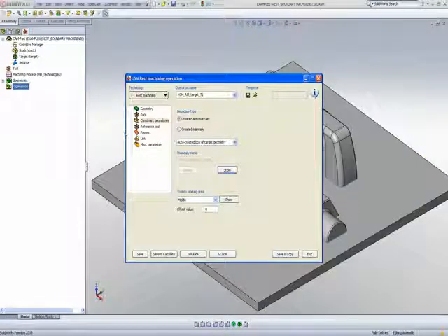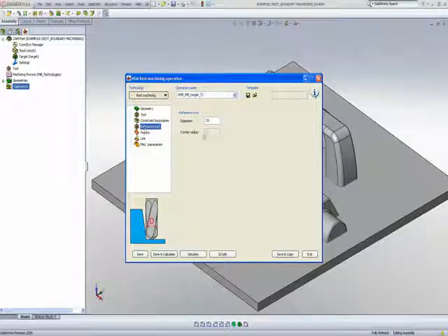And if I go into my reference tool, this is the area where I'll tell it what was the previous tool that worked there. The previous tool that I used, like I said, was an 8mm ball end mill. So I'm going to write down over here 8.2 so we can have a little bit of an overlap between the tool passes as we work on the part itself.